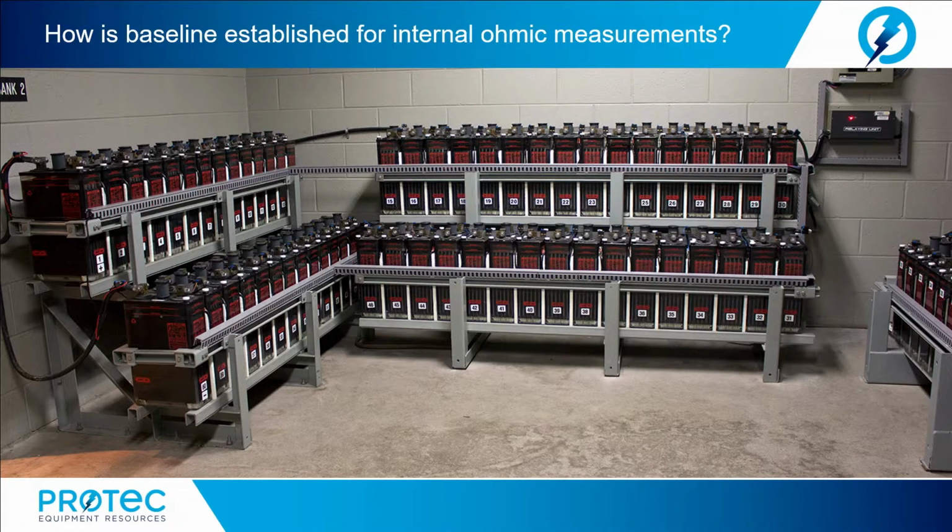Now, for all new installations of valve-regulated lead-acid batteries and vented lead-acid batteries, where trending of the cell's internal ohmic measurement to a baseline is to be used to determine the ability of the station battery to perform as manufactured, the establishment of the baseline, as described earlier, should be followed at the time of installation to ensure the most accurate trending of the cell or unit.